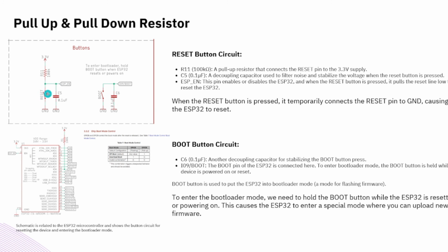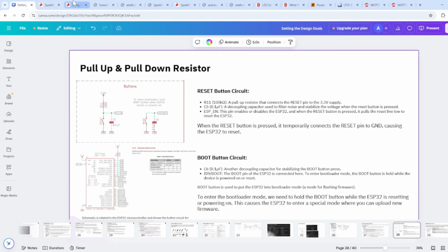Now let's see the other application. Whenever you are pressing this button, what happens? The moment you press this button, it gives a low impedance path, and the ESP is now pulled down. Whenever the reset button is not pressed, this will be pulled up. Same goes for the boot pin application, where you will see the moment you press this. So let me show you the full schematic so that you can understand this better.